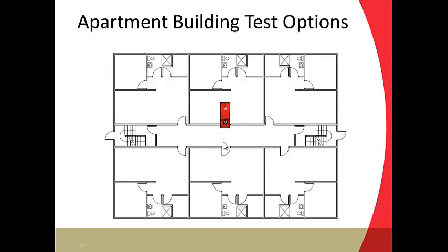So we've got conditions where we've got control of the building, and mechanical systems are off. All adjacent spaces on the floor above and floor below are open to the outside, so we'll get a common pressure across all of those openings, and we've got our fan running. If we want to do a guarded test where we guard all adjacent spaces, we would set up one fan on the left side and bring that up to pressure, and one on the right side, and bring that up to pressure.